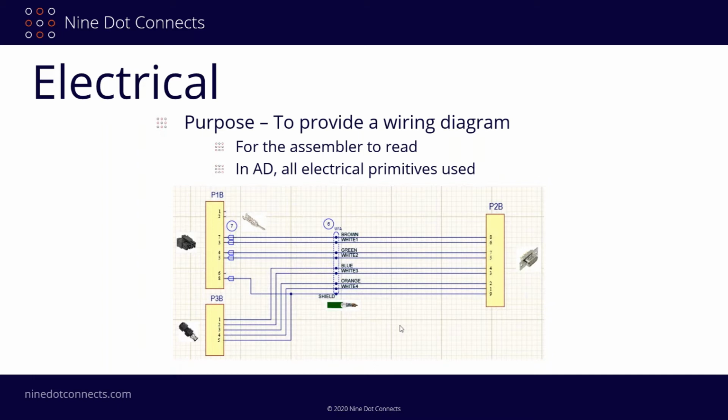We don't have a method to do that, but what I do believe is that if someone's savvy enough, they may be able to take a net list, put it into Excel, organize it, and then copy and paste that back into Altium. Or if they know some scripting within Altium, they might be able to put something of that nature in there as well. But that's kind of why you'd want to possibly do this here, is that that net list may be of some value down the road if you want to actually create that type of table. Okay? But you still can read this. That's the other thing too, it's still very readable just to read this. Just for a lot of pins, this can get a little overwhelming.